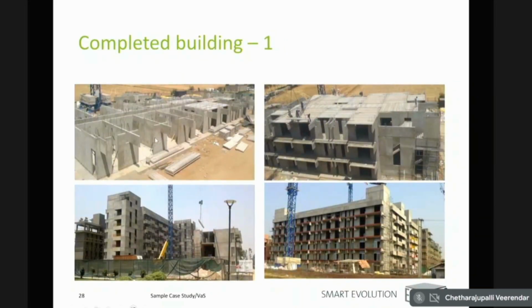Now you can see here, with a good design, even balconies are becoming part of the wall. We are not having it as a 3D element. So this is just an extension of the wall, and on top of this are going to be placed the hollow core slabs, which will become then part of this balcony structure.